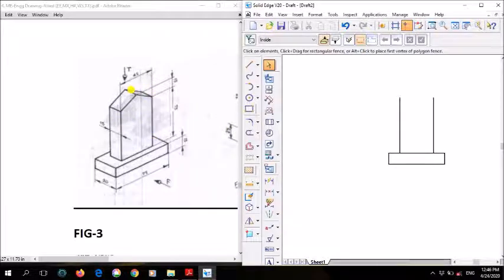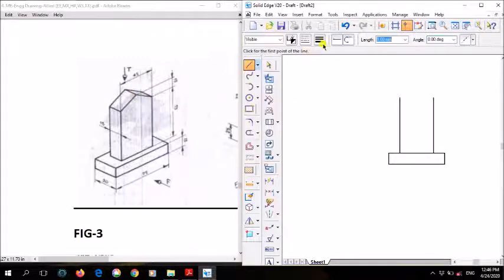So now the important thing is we need this part. Clear? We need this part. So using thin line now, this 75, you have a 75 line, so its center point will be how much, 37.5. At 37.5, mark a point, and from there using thin line draw a line. From here to here it is 75, and above it they have given 15. So add 75 plus 15, total 90 mm.